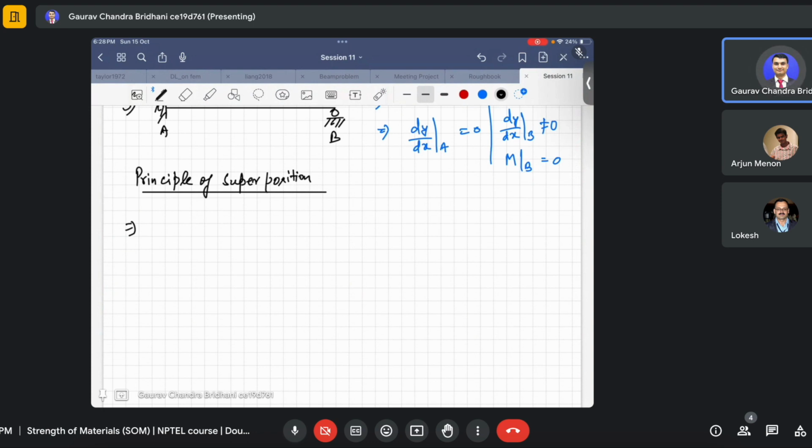And that is why, if you remember properly, while discussing the energy methods, basically the Castigliano theorem on energy methods, and specifically in the fictitious load method, the professor put a caution that do not use the superposition principle. Why did he put that? Because the relationship between the complementary strain energy U and the quantity M, which is bending moment, or suppose shear force V, or suppose axial load P, is not linear, it is non-linear. That's why we cannot use the principle of superposition there.